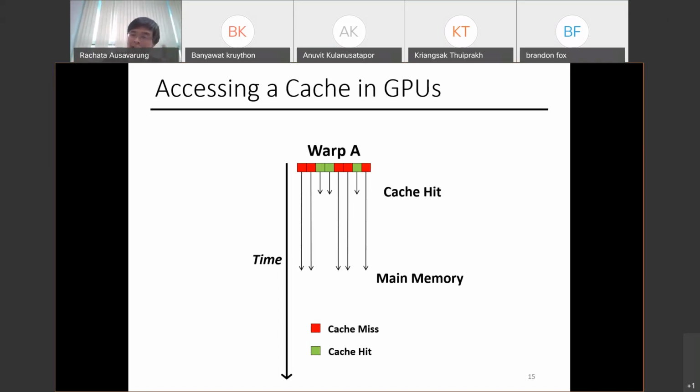So my question is this: if I look at warp A, when is the next time warp A is available that I can send the next instruction into the pipeline? Is it at point 1 or point number 2 that I label here? Time point 1 or time point 2? Anyone think about it a little bit? If I have warp A that behaves like this, yes, it's point number 2. That's when I can issue the next instruction.